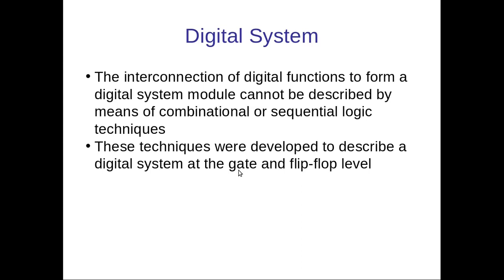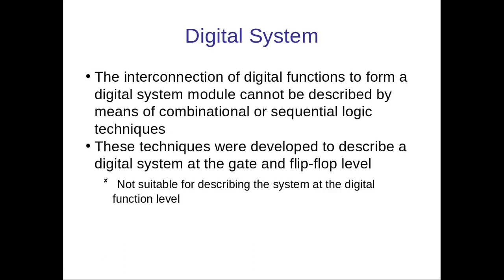So, in the case of very large systems that may contain a number of modules that we have to interconnect, it will be difficult and complicated if you are designing at the gate and flip-flop level, or using combinational or sequential logic techniques for describing that circuit. It is not suitable for describing the system at the digital function level.